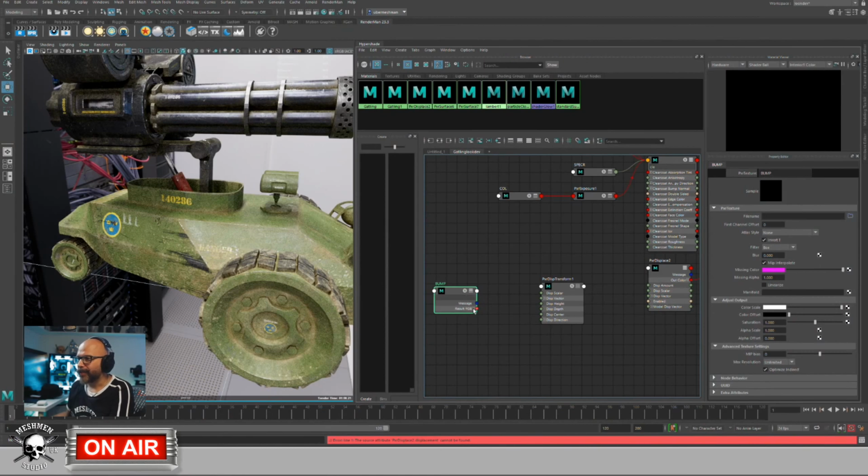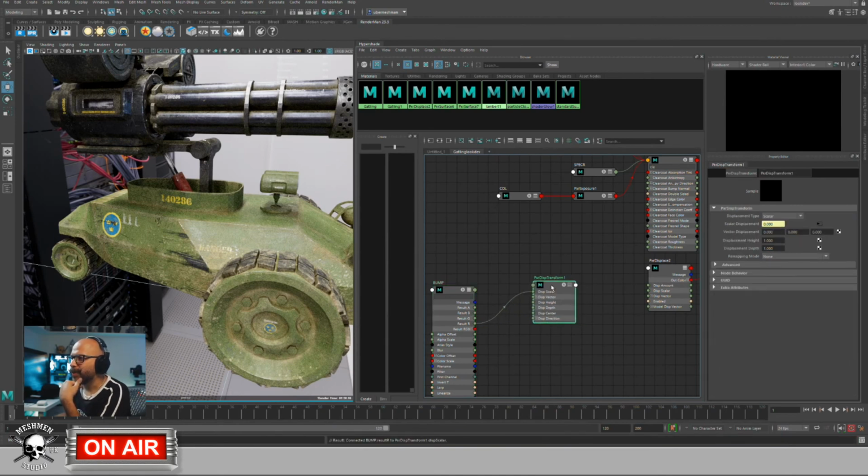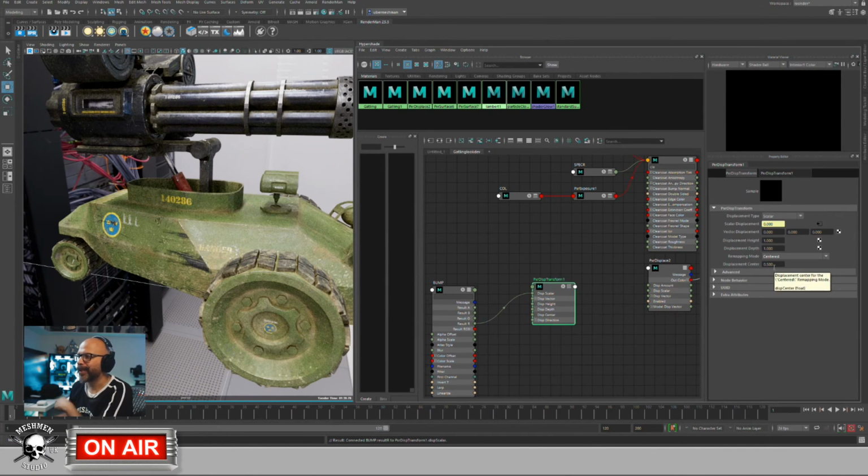And let's take my result RGB, or essentially I can just take result R and displacement scalar, and then we want to transform this. So I know that my base value was 0.5 and that is centered, and then you displacement center here, you can set exactly what value was your center value. And in my case, I always paint my painted displacements 0.5, because it's easier to look at something that has a value above 1 rather than having negative values.